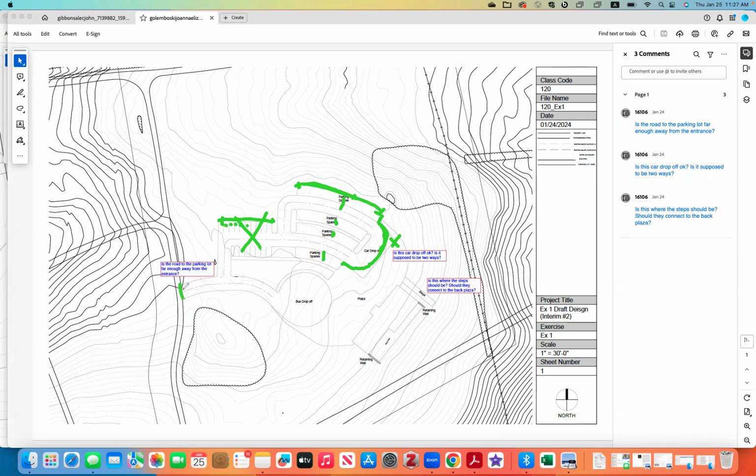So first thing, move this further away from the vegetation. Second thing, check the parking spots. And you are pretty close at the island in the middle here. I'm not convinced you have to start the sidewalk over here. If I'm dropping people off, that's enough space for people to be dropped off. So I can actually start my plaza right there. Same thing, I don't really need a sidewalk over there, so I can start my plaza somewhere here.